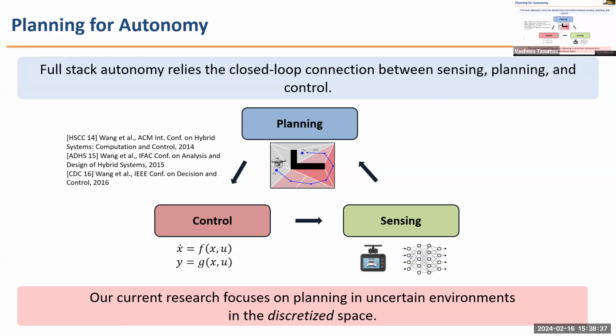So you want to do some abstraction, a simplification, reducing the model into the discrete domain. Basically, you chop up the continuous space into a finite set of states, and in that sense you remove a lot of complexity from the dynamics perspective and turn it into an easier planning problem to work with.